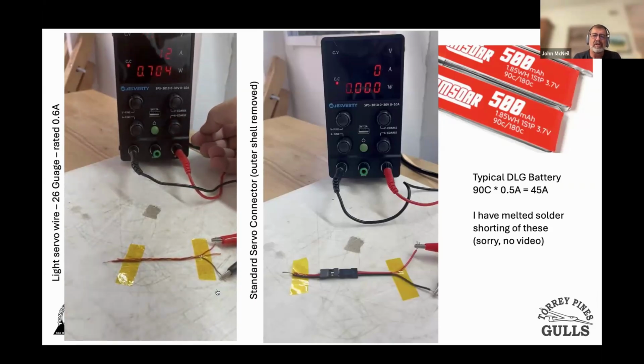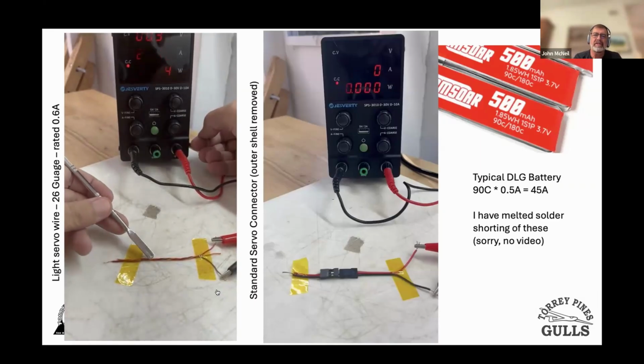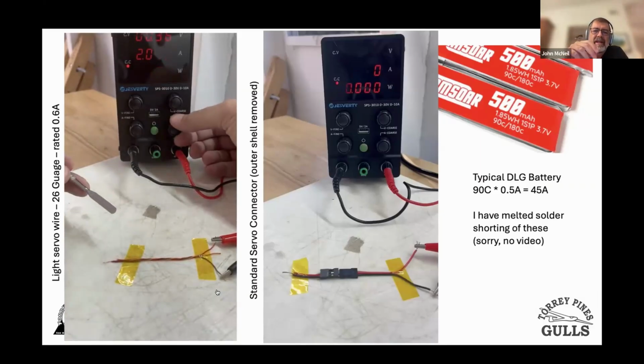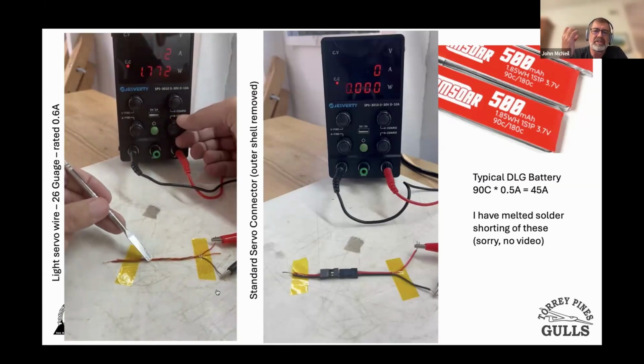As an aside, we don't solder crimp connectors because that wicks solder into the multi-strand wire, which then makes it stiff. And when it flexes, it will break. So crimp connectors have a crimp for the insulation and a crimp for the metal, and they're not designed to be soldered. If you want to, you could tin the wire, but you're not meant to solder them in those connectors. Even though the resistance would be lower, the break probability goes way up.